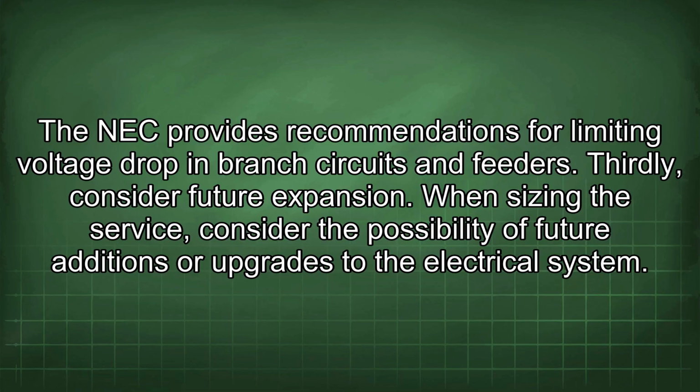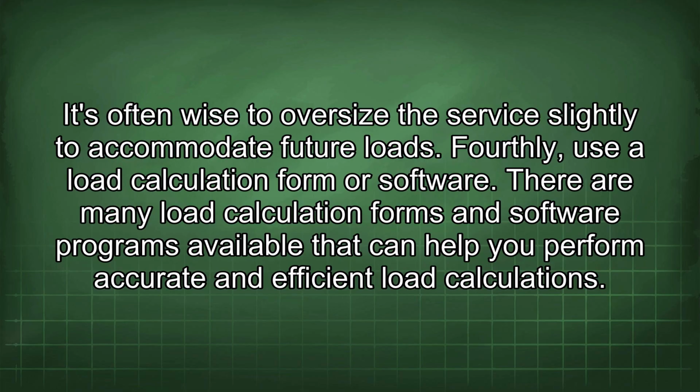Thirdly, consider future expansion. When sizing the service, consider the possibility of future additions or upgrades to the electrical system. It's often wise to oversize the service slightly to accommodate future loads.